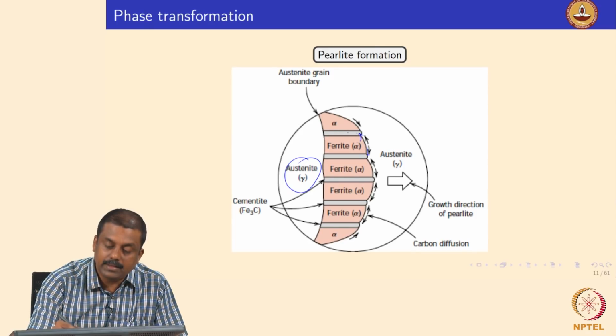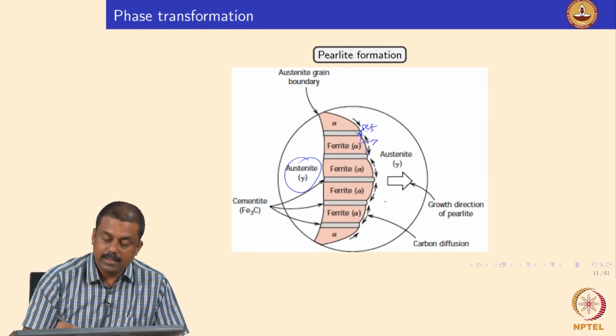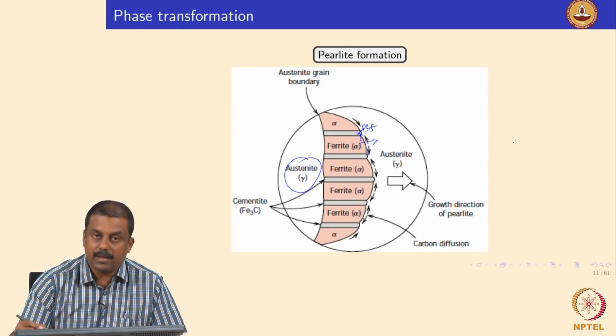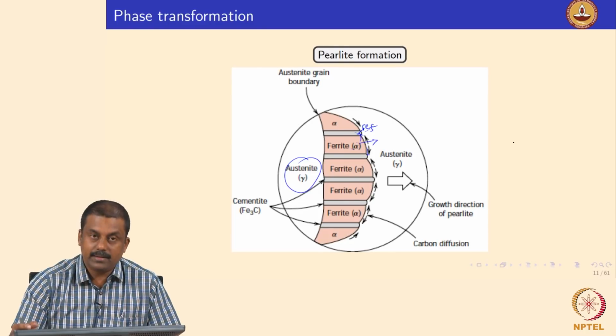The moment the segregation of carbon sufficiently builds up, you start precipitating cementite. Okay. So, subsequently this ferrite can grow by consuming austenite, and during this process the ferrite rejects carbon to adjoining regions, forming ferrite-cementite lamellae, as explained in this figure. And this happens close to equilibrium, when you do not have high cooling rates as well as high alloying elements.